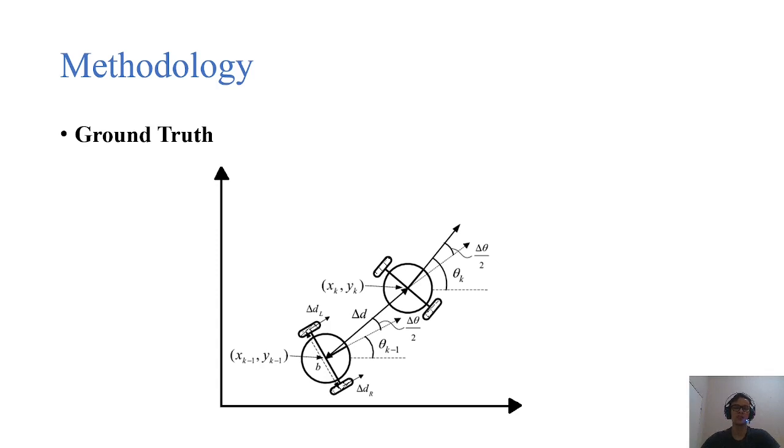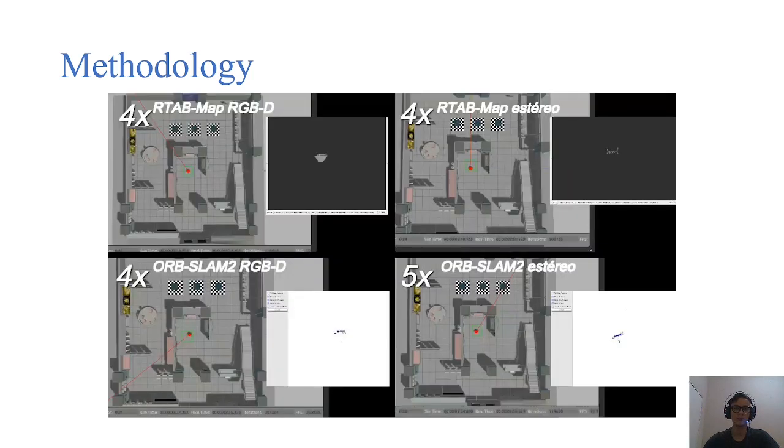But the question is how I get the ground truth trajectory to compare to the estimated trajectory of the Visual SLAM. And basically I used the odometry of the robot, with which you can predict the destination spot. It's easy to do, and I'll show in this video 4 simulations. I'll get started now.